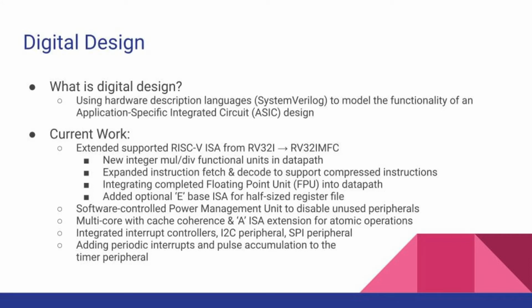The digital design subteam is a subteam comprised mostly of computer engineers, whose goal is to use System Verilog to model the functionality of the ASIC design. Their current work is mostly focused on extending the RISC-V instruction set architecture from RV32I, or the base 32-bit instruction set, to RV32IMFC. Each of these additional characters off of the RV32I corresponds to additional functionality.